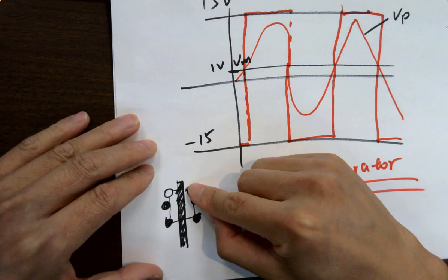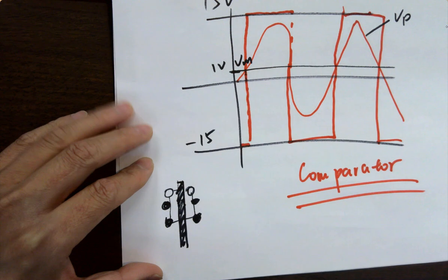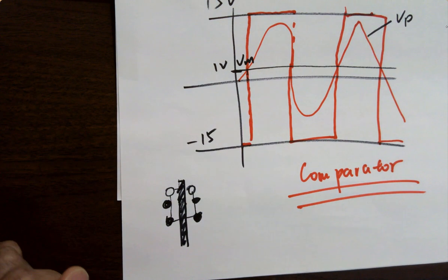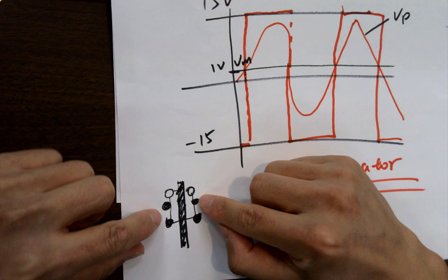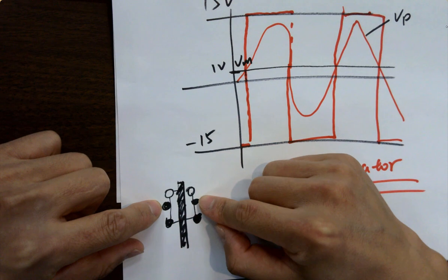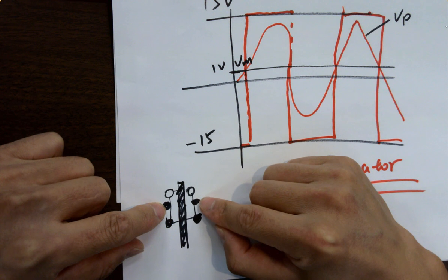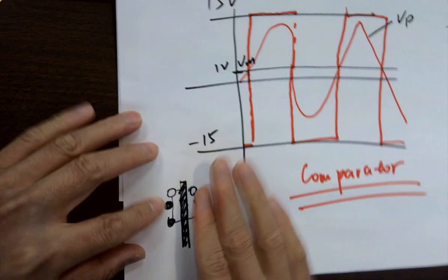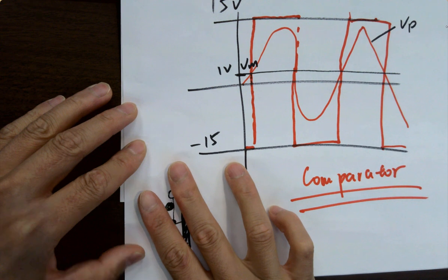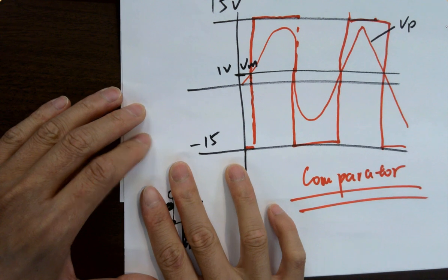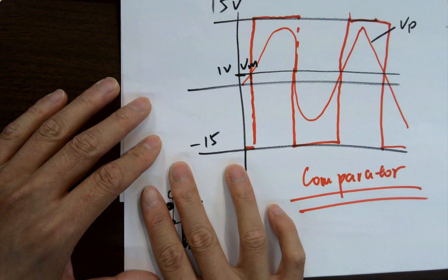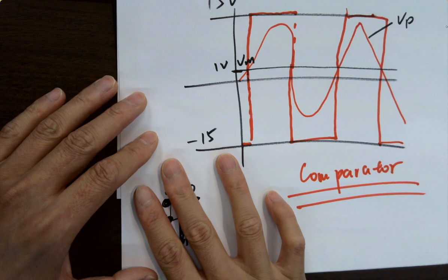So it's going to turn off. Which wheel do you want to turn off? Question I'm going to ask you. For example, I'm only driving the front wheels. It's a front wheel drive. It's not a 4-wheel drive. I'm only driving these two wheels, right? So if, for example, the car tilted that way, which wheel do I want to keep on, and which one do I want to stop to put it back on track?